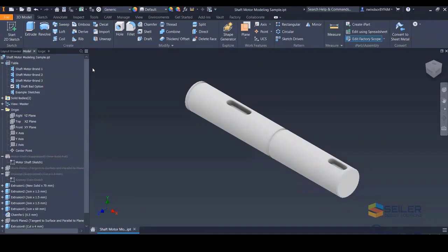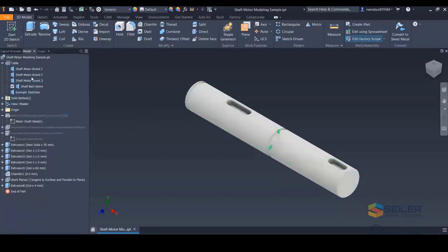If you have something you're always working with, flanges or say this motor shaft here, you always have a cylinder with, you have to capture the motor. So you've got your snap ring grooves. You have to get it to turn. So you've got your keyway slot. Every motor shaft is going to have these 2 features. They're going to have a specific length on the end for the drive sprocket and then a specific length based on the motor. You can actually put all this stuff into a template. You do your base part file with all your features, and you can do a Save As template.